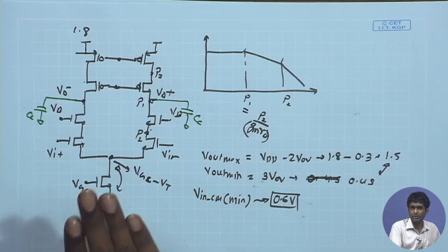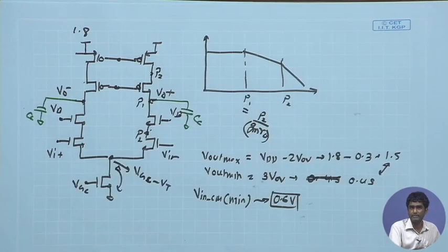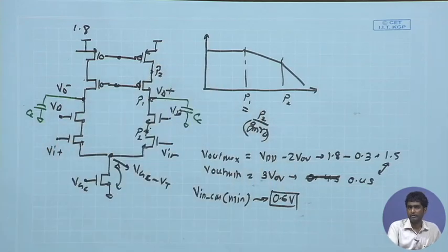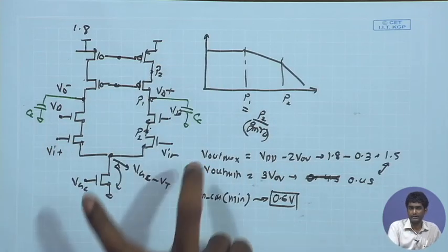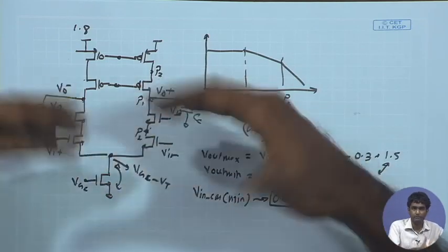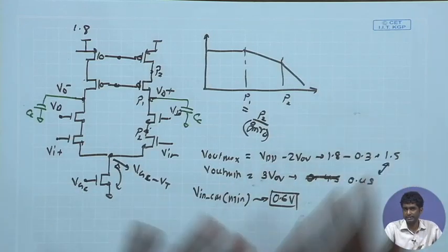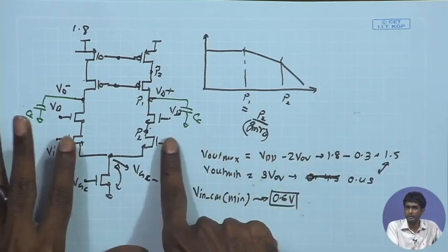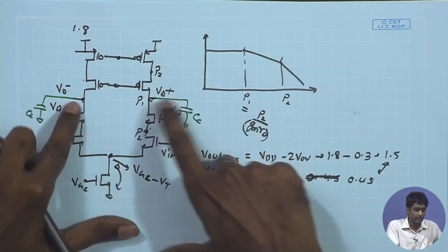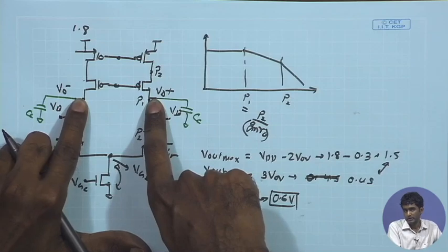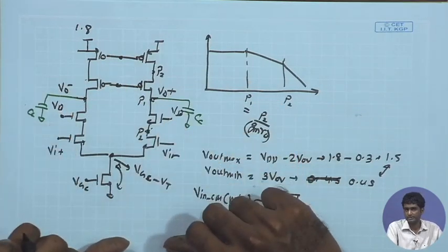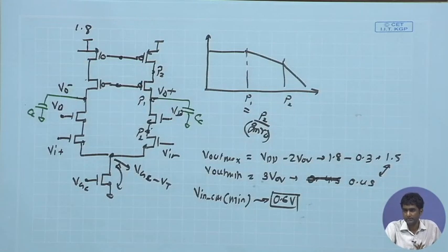So, any question before we try to look at an alternate scheme, which is a folded cascode scheme, which can resolve this issue of DC bias and the swing, at least the input swing. And then also we have to look at a biasing scheme through which we can get the best possible output swing. So, these are the next discussions, looking at the folded cascode topology, where the constraint on the input swing and the input DC biasing is resolved, and second, the output swing considerations, where I need to set up the appropriate bias point for these transistors so that my output swing is maximized.